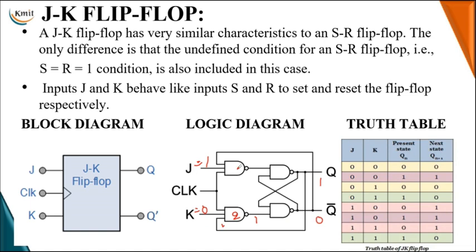So next, if 0 is transferred here, then the first NAND gate output would also generate your logical 1. So if 1 1 are there, there is no change in the state. So this state is continued as your next state. So here 1, here 0 is transferred. So hence 1, so 1 1. So here, set state.